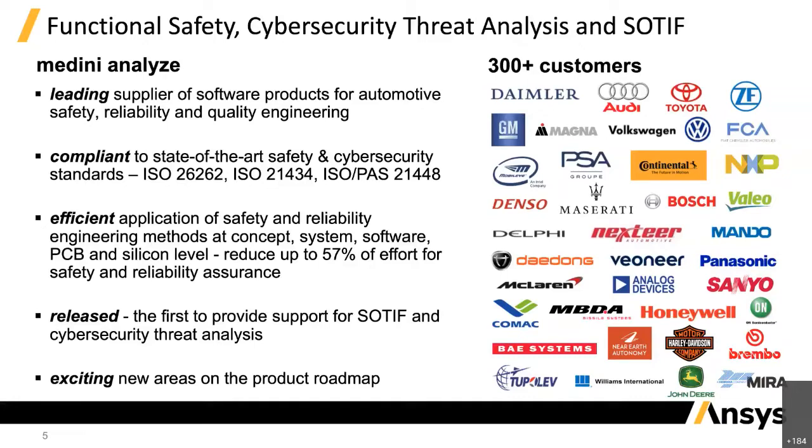For example, you want to reduce the risk of cybersecurity, in which case you hope to encrypt the messages that are being communicated over the data bus. The moment you bring in the encryption, the sender should encrypt the data and the receiver should decrypt the data. So that adds to the delay or the processing time of your messages, which probably affects the functional safety, your FTTI timelines, and so on. So that means there is a linkage between functional safety and cybersecurity, and in some way to SOTIF as well. So performing all of these analyses together in one single solution provides you the best of the combination. So that's another area where we are working on.